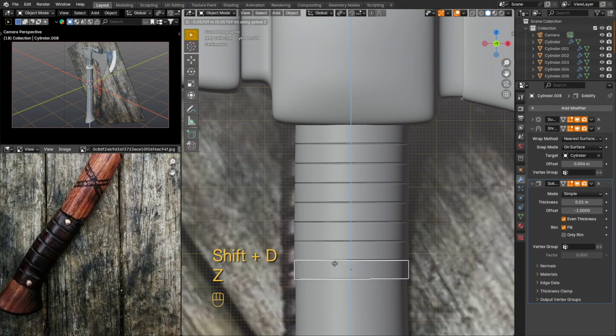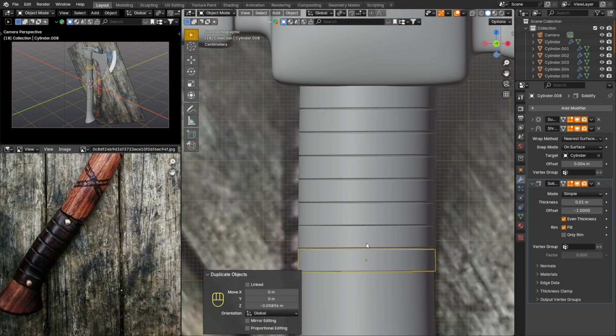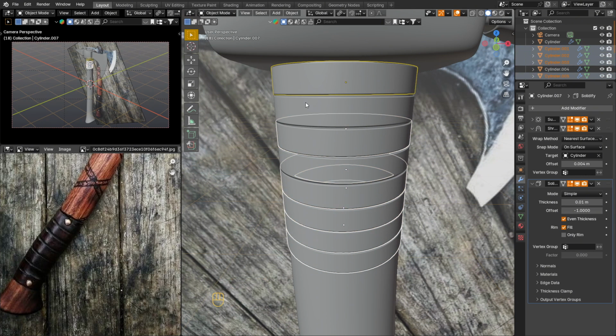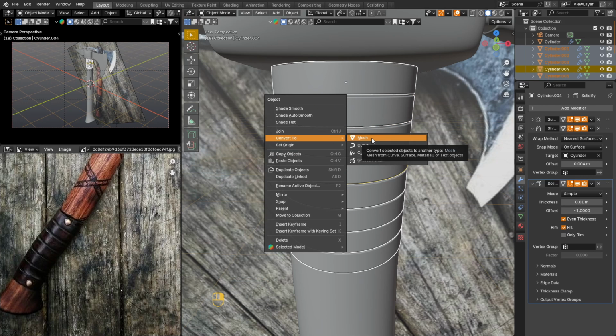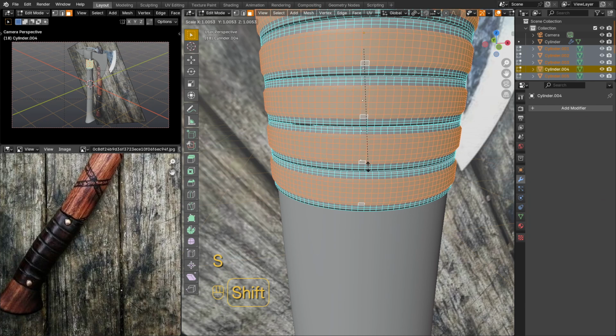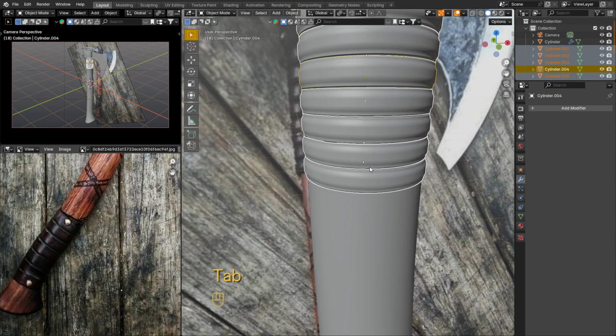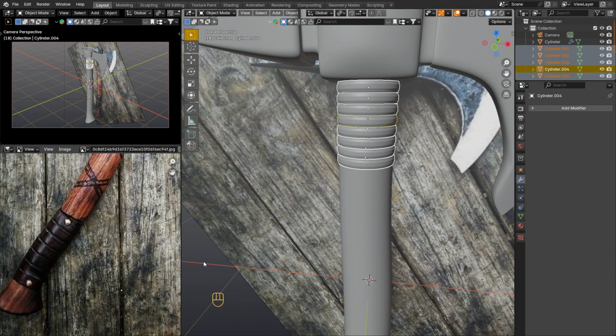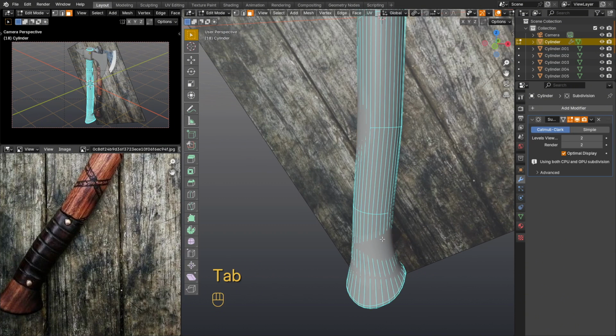Now that we have them on the axe handle, with the Shift key pressed, select all 8 pieces and transform them into a mesh, which means that we apply all the modifiers to these parts. Now we go into edit mode and you can see that the selection that was originally there has remained. And I want to slightly expand these elements in diameter, in order for everything to work correctly. Individual origins must be selected in the transformation pivot point.